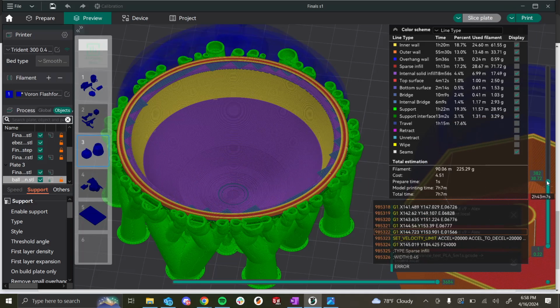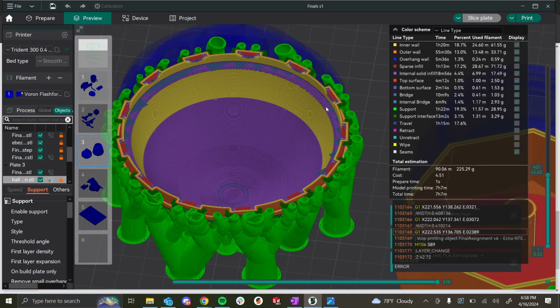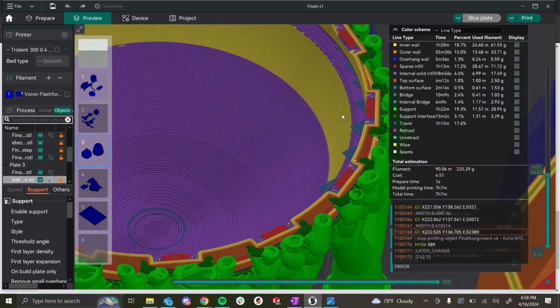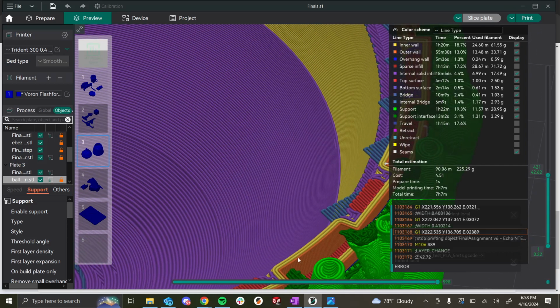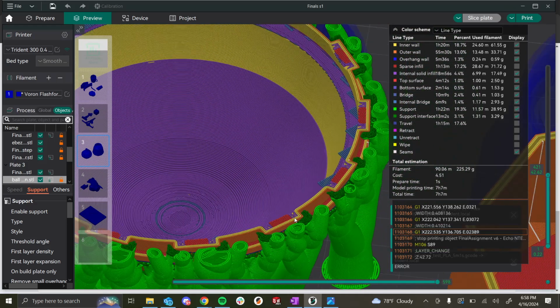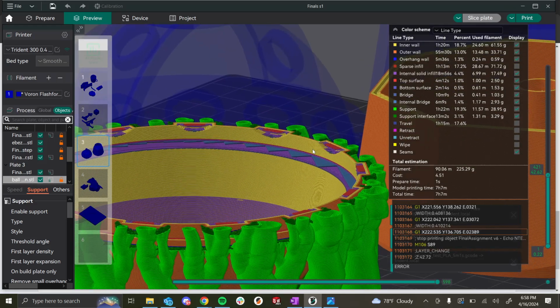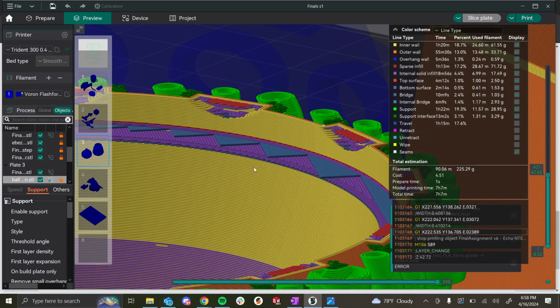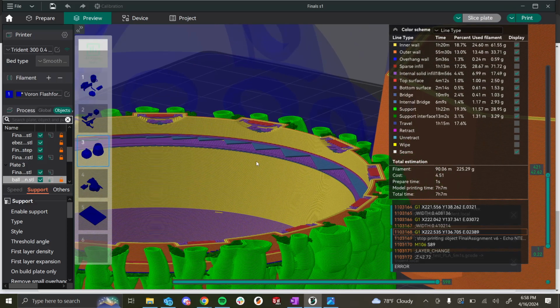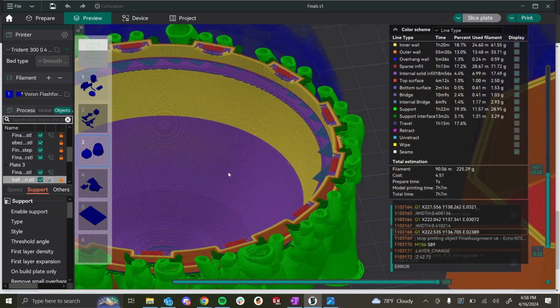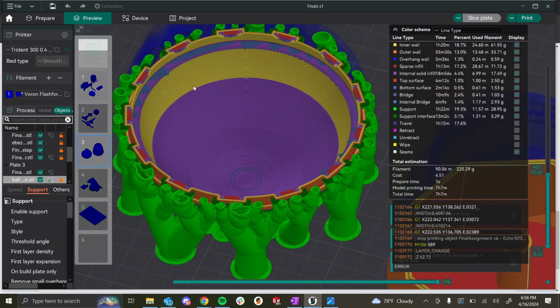But yeah, if you look closely here, zoom in. This is only like 2 or 3 perimeters worth of material. The slicer is doing a lot of weird stuff to try to recreate the model. It's bridging in midair for no reason and stuff like that. So the slicer's just kind of getting confused. So if you do send me something hollow, make sure it's a nicely sized thickness, because if it's too thin, it'll be a lot more difficult.